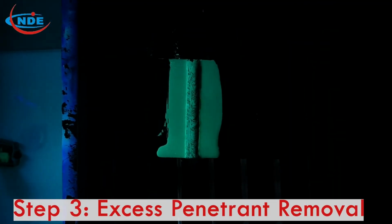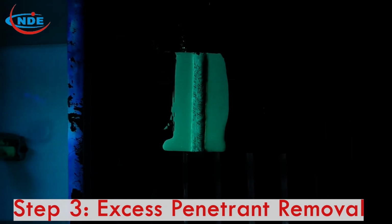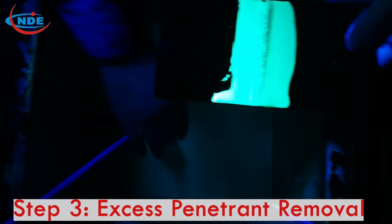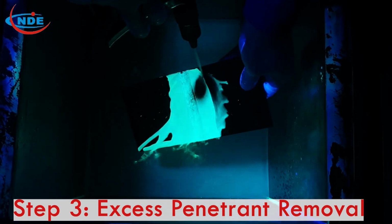Step 3. Excess penetrant removal. Excess water washable penetrant should be removed by spraying water with a suitable pressure.